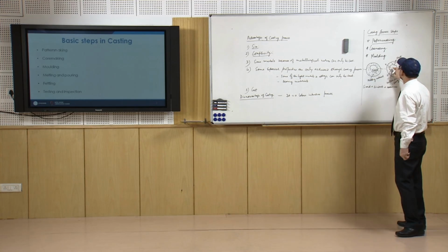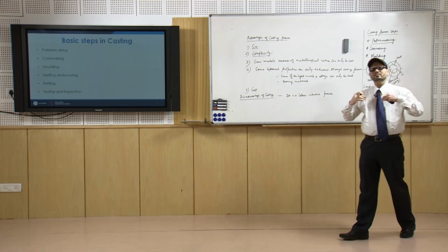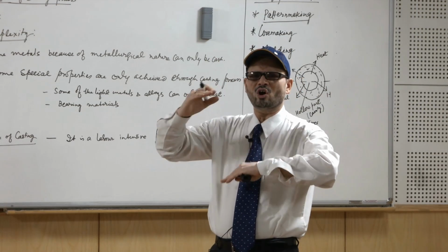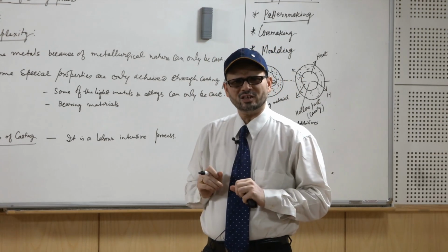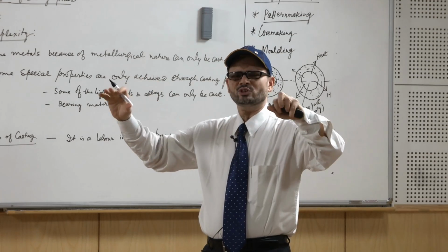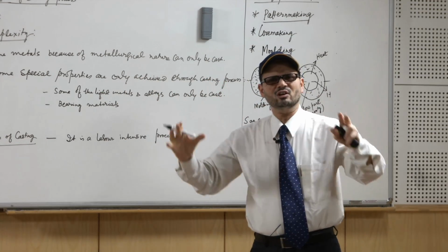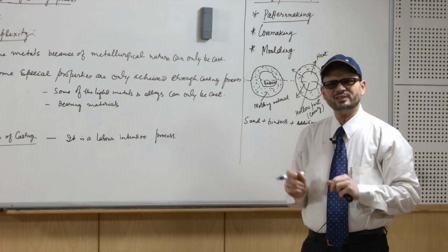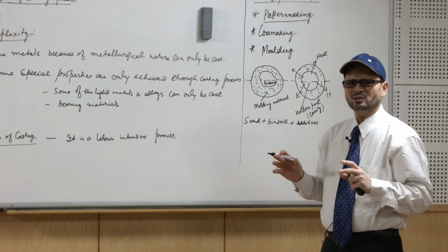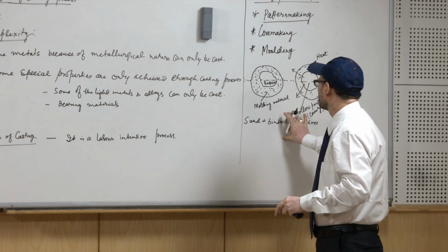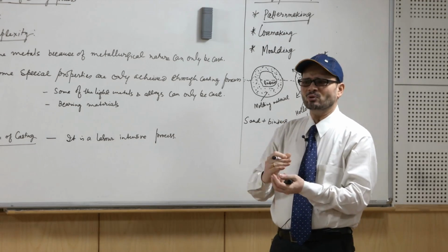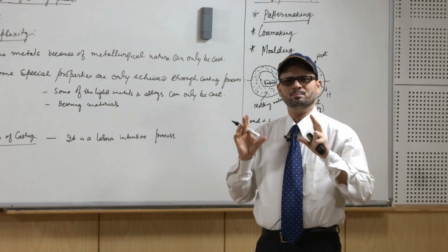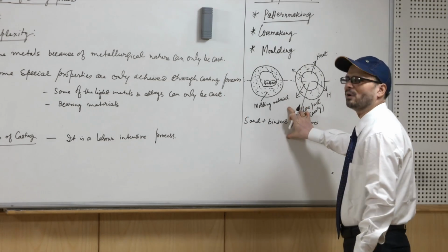So, in the molding section you have different kinds of molding boxes. You have bottom, top and middle molding boxes. You have different units for basically mixing of sand. You have units for the baking of sand, baking of the mold, and once that is ready, then when the pattern is removed and you have baked the unit, your mold is ready for the pouring part.